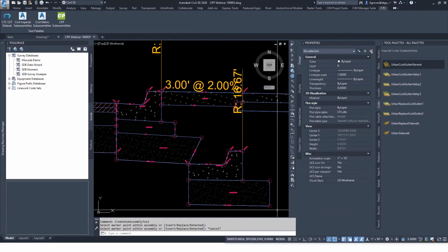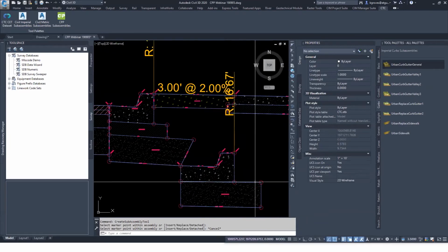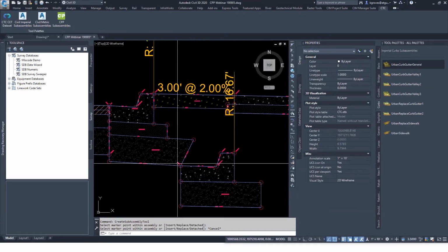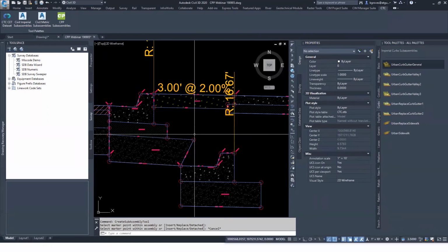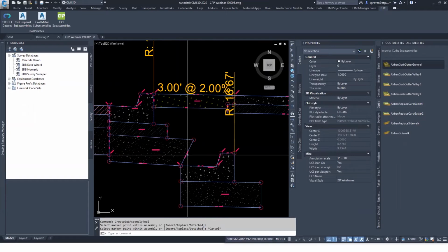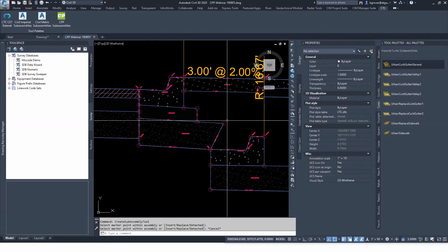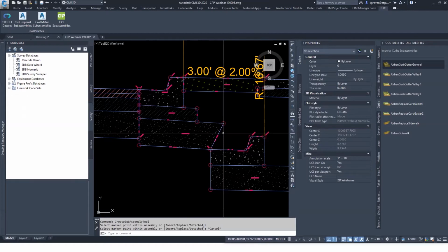So one thing I noticed right away for this out of the box curb is that my sub base has a vertical link for the edge of that, whereas the CPP has this kind of diagonal link. Well, that goes back to when you're building a surface and what overhang correction you're going to be using. When I go out here and build this in the field, not everything that I build is going to be able to maintain a perfectly vertical slope. And Civil 3D really hates to calculate multiple Z points at a single XY coordinate. So this is going to help make sure that you're always going to get your most accurate quantities and also your more realistic build conditions for being out in the field.